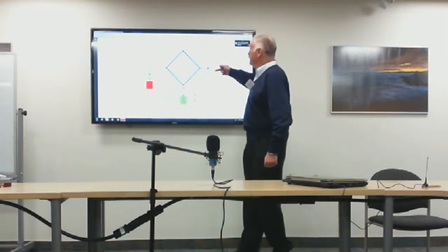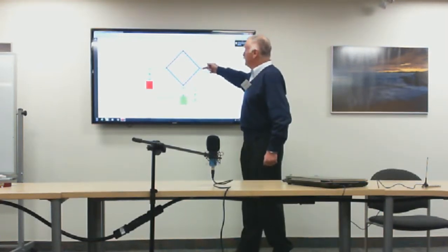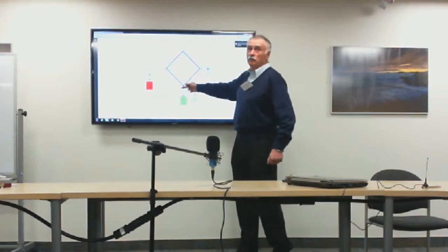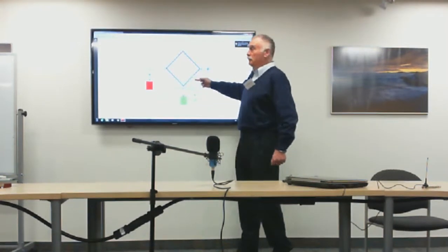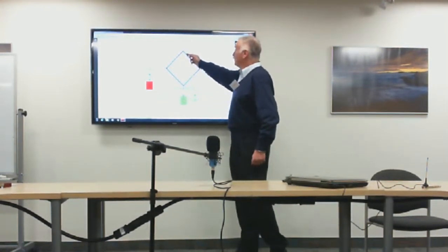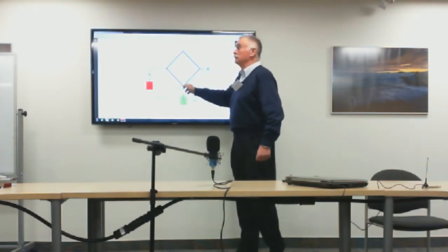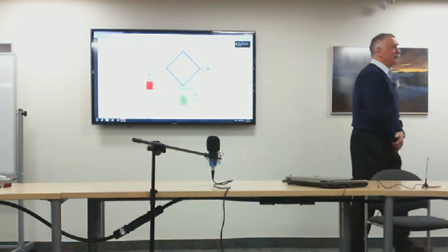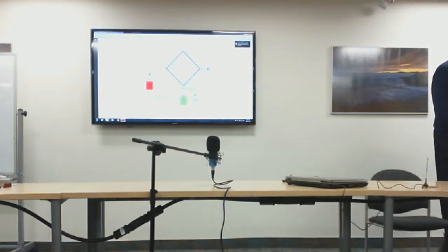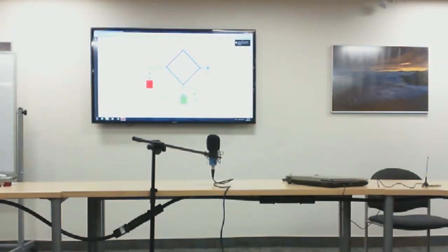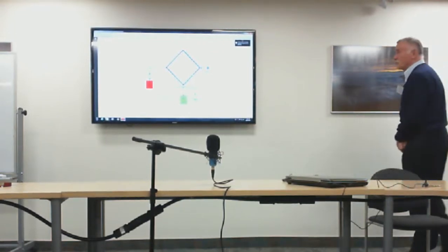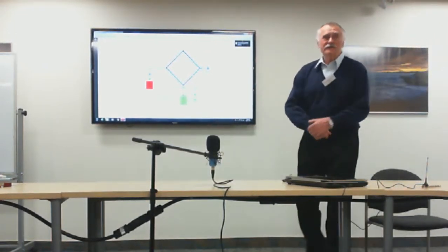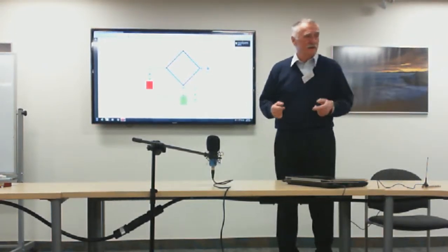So any signal from the antenna can go two ways. One way down to the receiver over a quarter wavelength line, or the other way up a quarter, a second quarter, and a third quarter. But when radio frequency travels odd multiples of a quarter wavelength, the signal returns into the same phase.